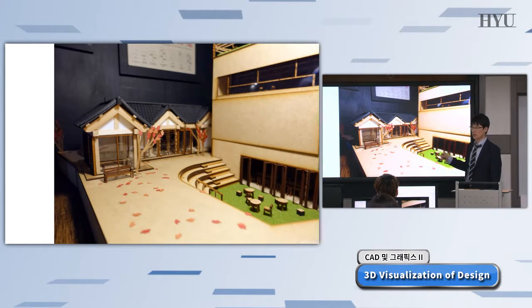The laser beam is really high temperature. Because of the thermal effect, the wood burns out, okay? That is why the surface or edge of this line is black, a very dark brown color. But close to that cut edge, it is light brown, simply because of the thermal effect, okay?